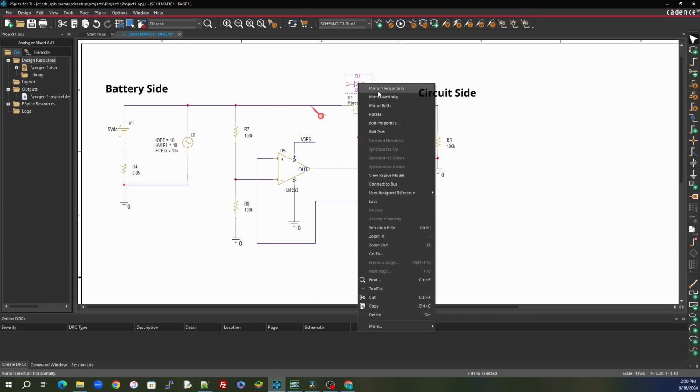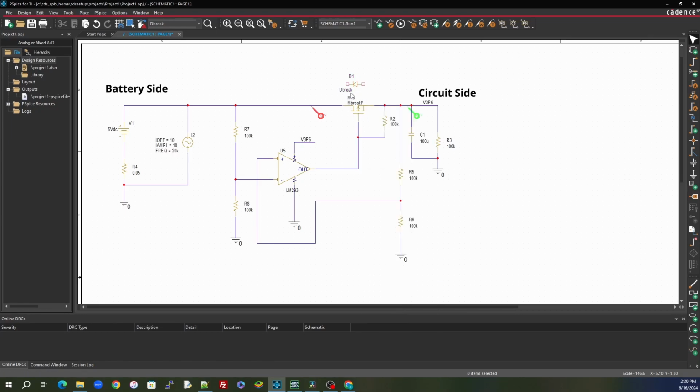Normally I'm not using this PMOS as a standard PMOS high-side switch. Normally in a PMOS, you would put the source on the supply side and the drain on the load, because it's got a body diode. When you turn the PMOS off, the body diode would block the supply from supplying current to the load.